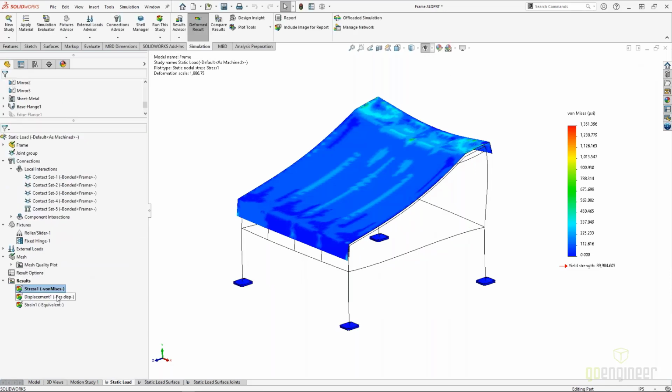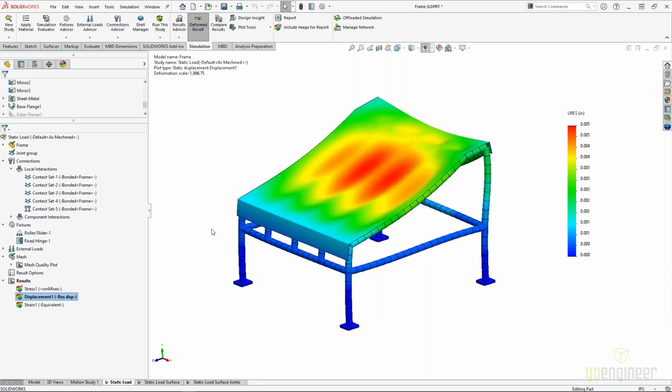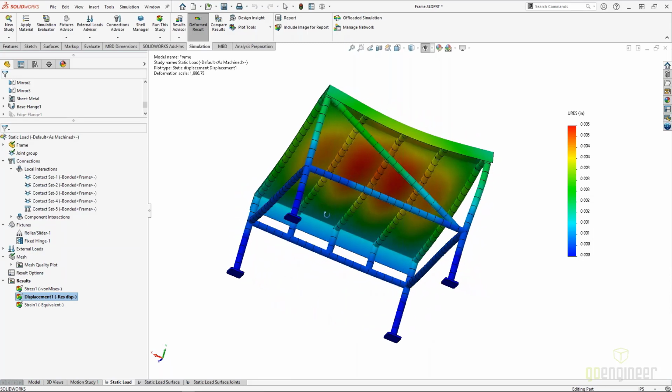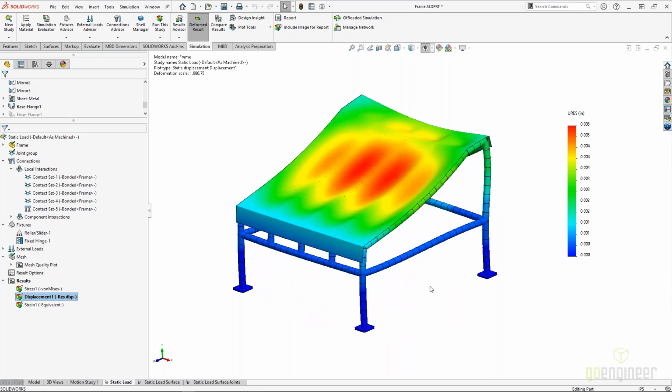Now, the one thing that we can look at together is the overall displacement. So you can see that with the beams, you can see that with the shells and the solids with respect to the output. So that's a mixed mesh environment. The biggest thing with that is to appropriately understand your interactions and how the different components all work together, and then what you're really getting for the output. You're getting a von Mises stress and normal stress and principal stress for the shells and the solids, and you're getting your axial and bending stress for the beams themselves.